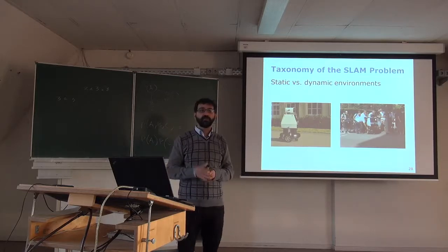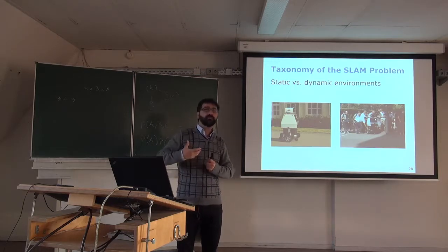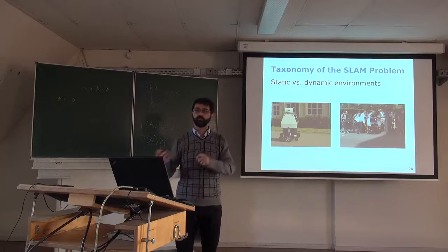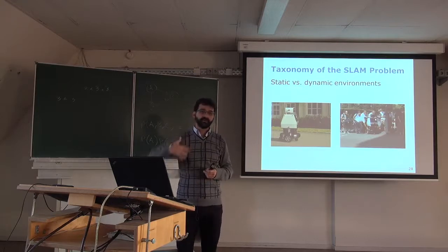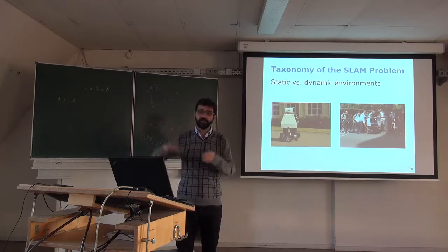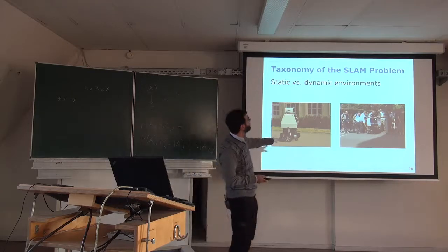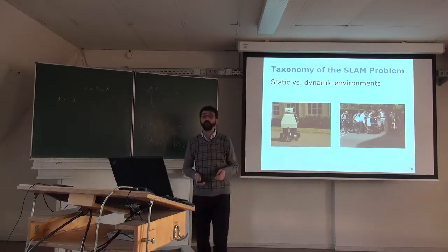So you need to be able to reason about things that you might know move or not move, or about your internal state and your internal sensor, your odometry, saying, my other sensor tells me I'm staying still, so only the world can move and not myself, okay? So that's the additional problem you have when you are in dynamic environments.